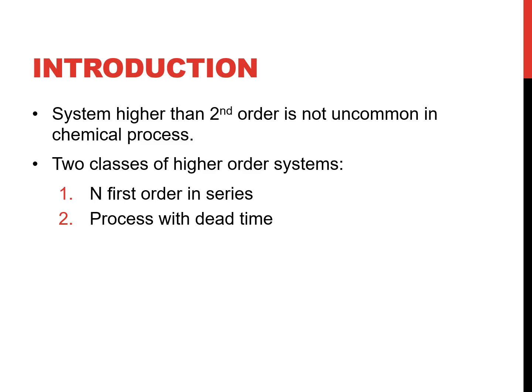So if we try to measure the temperature inside the distillation column, the measurement will be transmitted through the piping line, the electrical line, into the thermocouple and into our monitor. By that time, we sometimes have a delay, maybe 1 second or 2 seconds. So this combined with the transfer function of the distillation column becomes the higher order system.